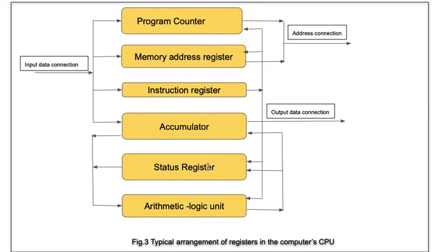Next, the status register. Status registers are used to indicate the internal conditions of the CPU. A status register is made of 1-bit registers, often called flags. The flags, or 1-bit registers, are used to identify such conditions as logical decision outcomes, overflows, and interrupt conditions.